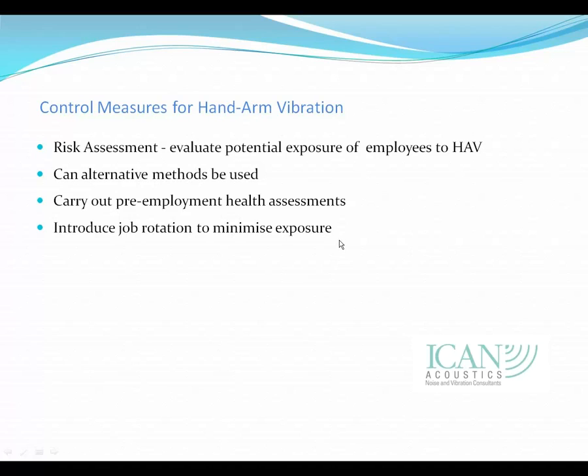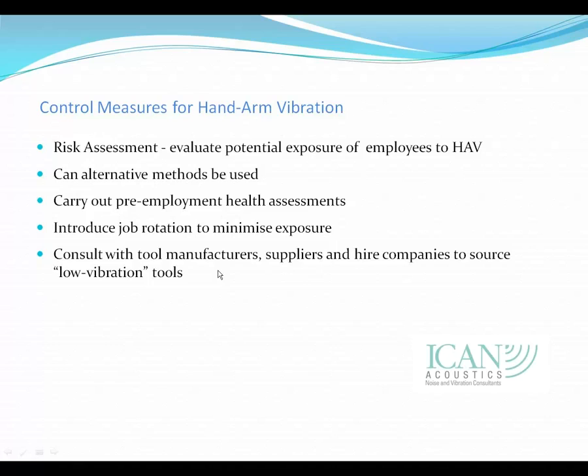Another important thing would be obviously to consult with tool manufacturers and suppliers, hire companies. Is it possible, for example, to source low vibration tools? As I said to you earlier on, a lot of the market leaders are developing improved technologies where there's better decoupling between the tool and the actual handle. And in such cases, it reduces employee exposure to vibration.